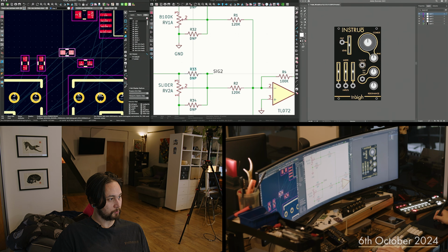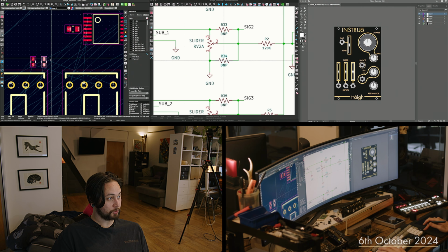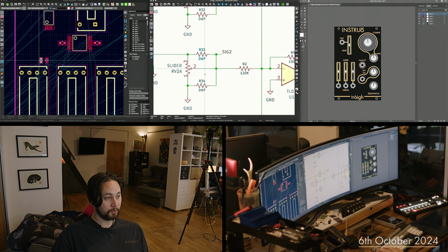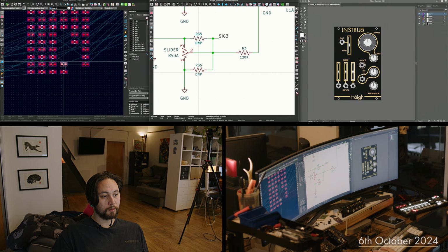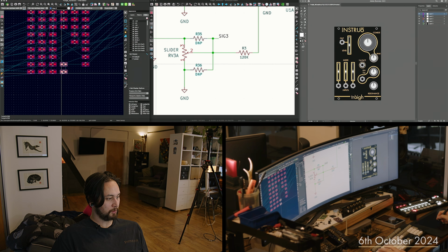What's going on? So they're moved exactly on top, but I can isolate just them by selecting them in the schematic. There and there. And then move them exactly by 12.7. Perfectly placed. And we'll do that once more. This is really handy if it's a bigger repeating circuit, like parallel groupings of CV buffers or something like that, which is the same circuit multiple times.